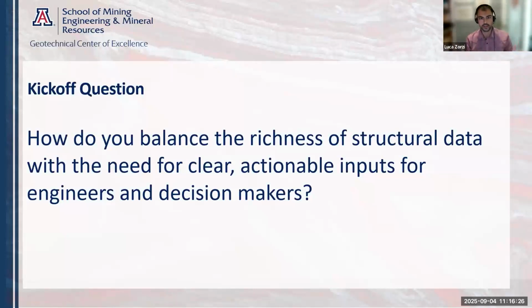The easiest one is that we do see structures that are very thin, less than a meter of damage zone in total, so the core is even thinner, and then they show up as this 20-meter zone of very weak rock in the numerical simulation, because that's the mesh size they're using. So there has to be an additional, constant communication to make sure we're not overblowing the interpretation during the numerical simulation, so that it's not representative of the reality.